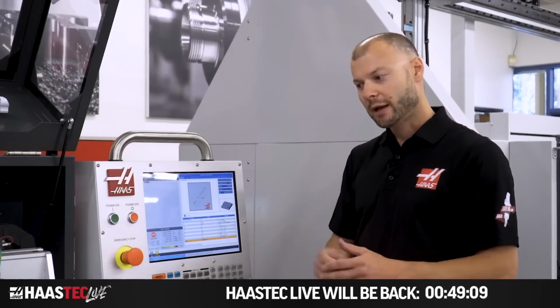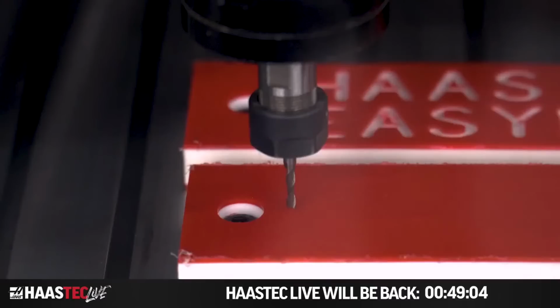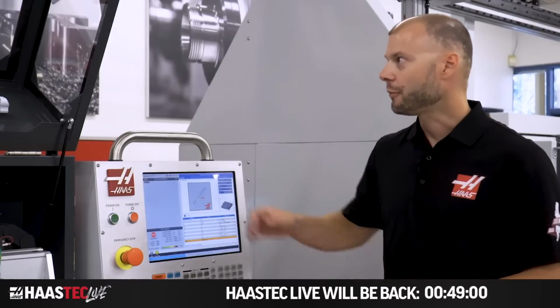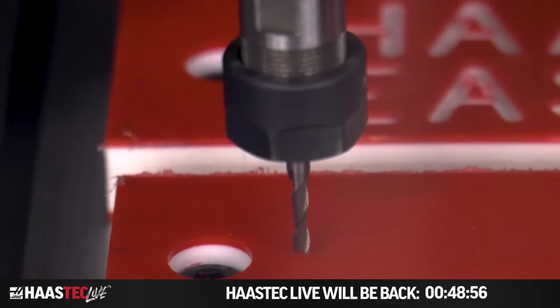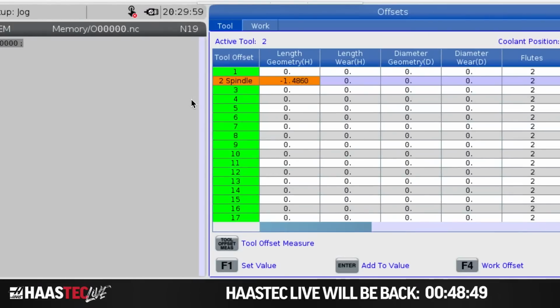But before I do that, I'm going to move my machine away from the stock a little bit, in case I entered any bad numbers. I want some time to push stop. So the first thing I'm going to do is move Z away from the table a little bit, just in case I got anything wrong. This will give me some time to realize that and stop it before I crash anything.